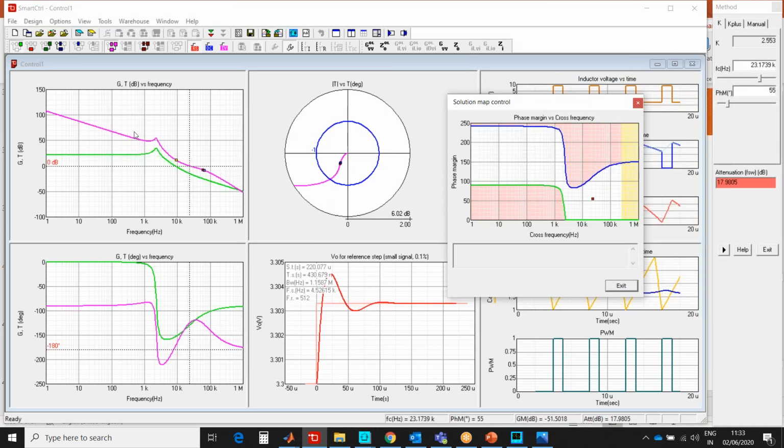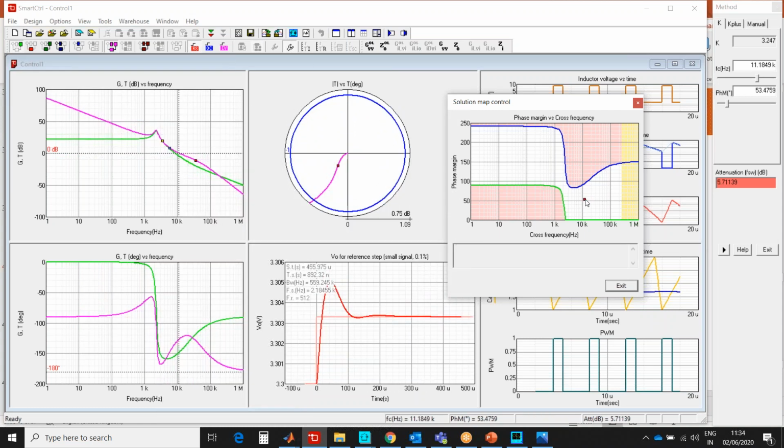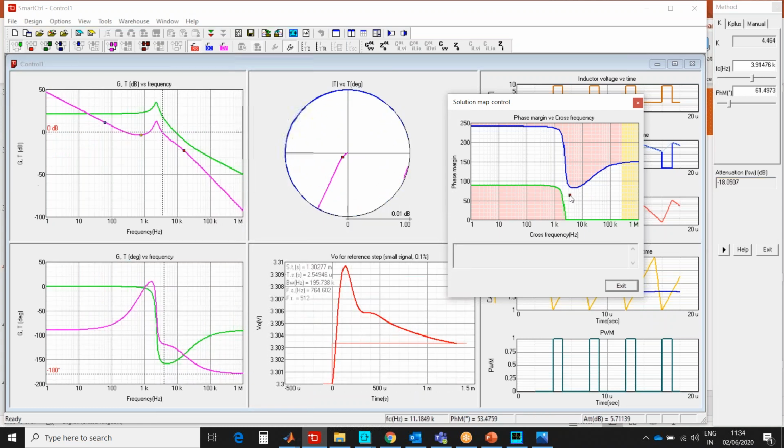So for example, in this we have different plant models. So one is my control output transfer function, and this green one is my plant transfer function. So in this, you can see my poles and zeros, which is already available. So now we can tune the parameters. In order to tune the parameters, we can just drag your point. Accordingly, this entire values will vary.